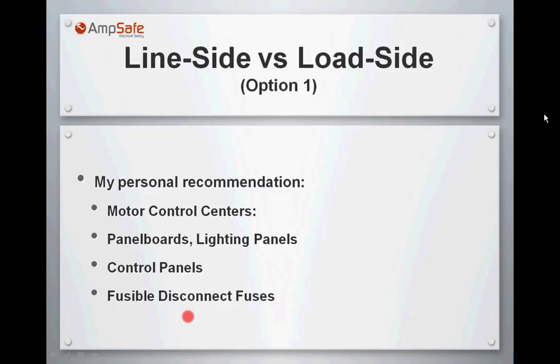And you have to sacrifice the whole panel because of a little section on the line side of the main overcurrent protection device. But nobody can assure you that there is not going to be an arc flash at the line side of that overcurrent protection device. So in that case, I definitely put control panels as the worst possible case, which is line side.